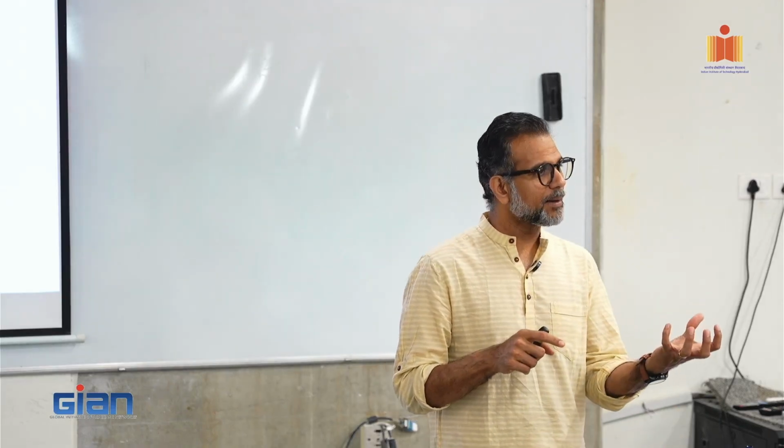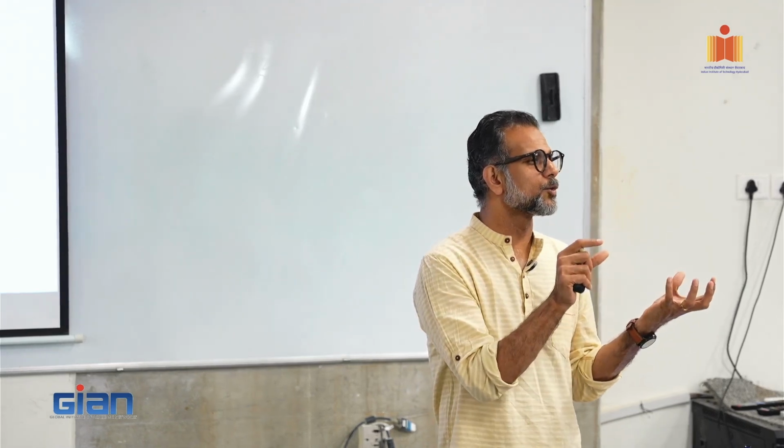Other questions? Not for thixotropic behavior, because what happens is with the mini slump, you can kind of do it, but the problem is the variations are going to be so small that you can't pick up anything. So you can take the test, do a mini slump, remix it after half an hour, do a mini slump, and you probably will get the same value.